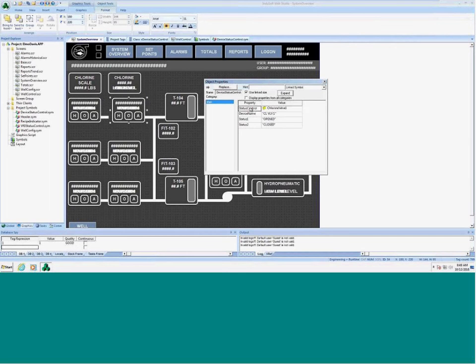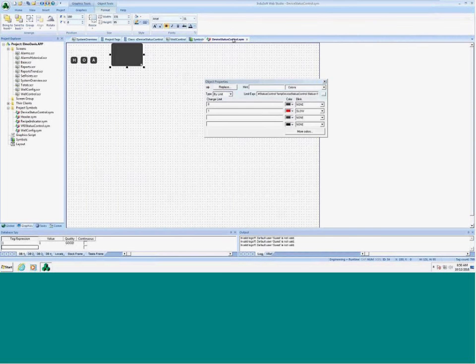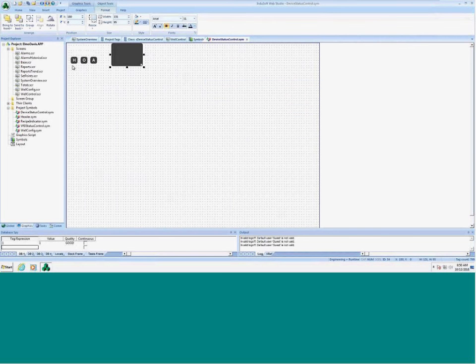And then this status control, you can do just integer properties or string properties, what have you, but I actually did a property that was a class tag. So I was taking advantage of class tags to keep that structure, but then I'm also passing that whole structure in. So this chlorine valve 1 is a class tag. And then to actually get those individual tags, statuses, I guess I have to move this stuff around.